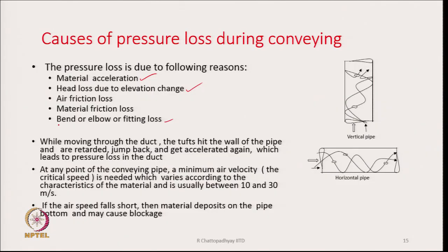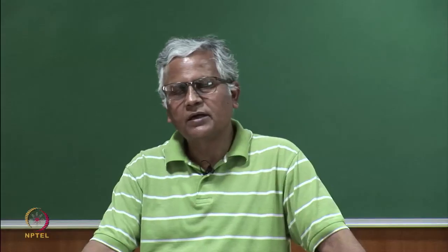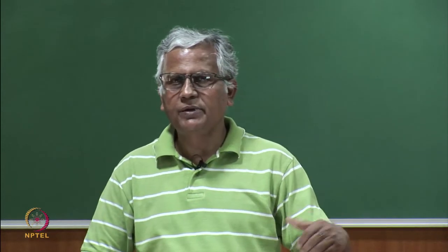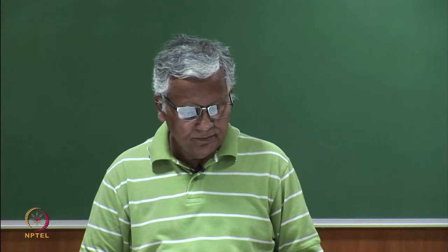The last point is the bend or the elbow or the fitting loss. Wherever there is a bend, the air has to take a turn, and hence there is a loss of pressure. So, there are many reasons why the pressure will be lost as soon as we feed the material in the duct.